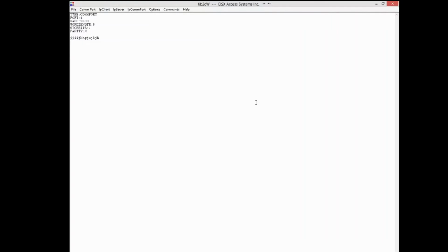At the panel, disconnect the transmit, receive, and ground wires from the master panel and twist them together. Type any letters on the keyboard. If the letters are displayed, your connection does not have a proper signal ground. There is an open in the ground wire or it is wired wrong at the COM port. If the letters are not displayed, then the serial port is functioning properly.